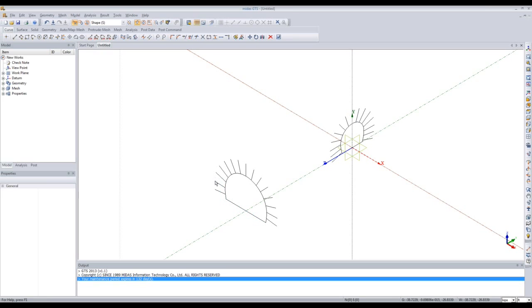Now what we need to do is create a different geometry set for the rock bolts. Open this, here's the Worktree menu. Open the Geometry tab, and then you'll have all these options. We don't have any of these things created yet, but we can create a new geometry set. That way we can select certain pieces by sets for convenience.